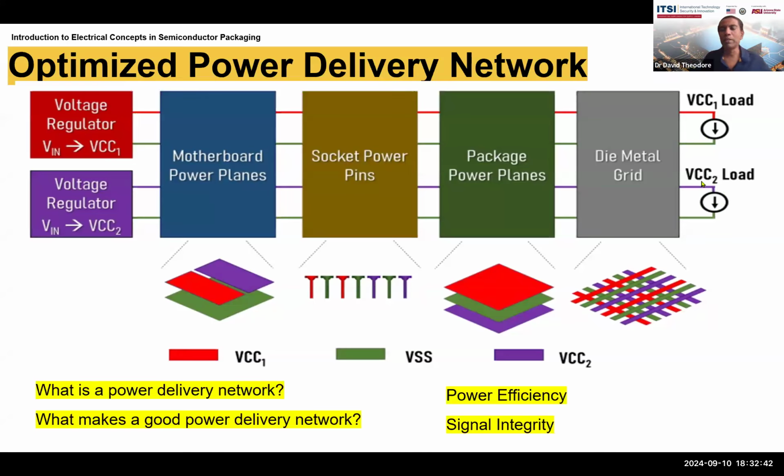Now, the reason why you would separate the two of these out is there are some chips that actually have two different voltages to different parts of the chip. That's unusual, but that's sometimes done. And in some cases, even if both of these voltages in are the same, you may want to isolate these two circuits to avoid crosstalk or cross-contamination.